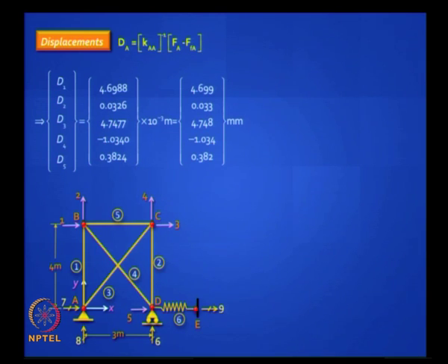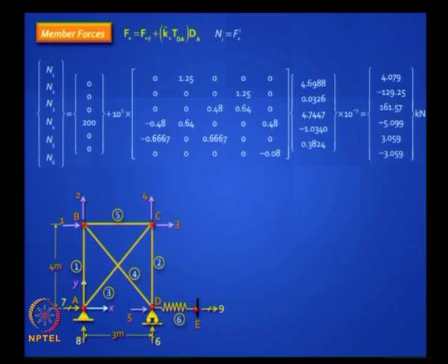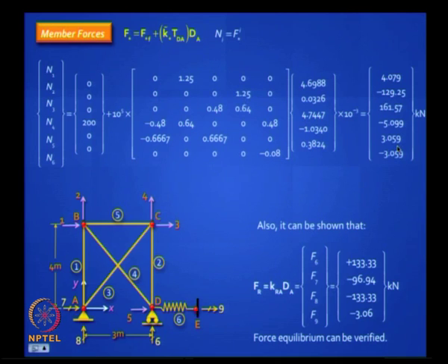You've got the answer, then what do you do next after you've got the solutions? You've got the unknown displacement, but that's not what you really wanted, you wanted the bar forces. So to get the bar forces, you remember you've already computed this and you are ready, you got the initial bar forces, there is one 200 kilonewton already there, this FFA, remember, and then you do this operation, you get these answers. And if you want, you can also find the support reaction if you bring in TD R into picture. That is it, one problem, understand fully, and you can handle it.